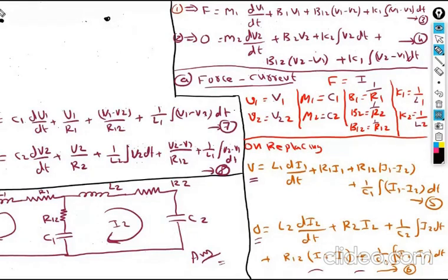As usual, in terms of electrical engineering, I am giving the names of voltages V1 and V2 to the junction names. So now here the first element, since I is on the left hand side, I am writing the I expression. What is it the sum of? C1 into dV1 by dt. It means that directly I can write here one element, capacitance, like this. Now next, one element is there, R1.